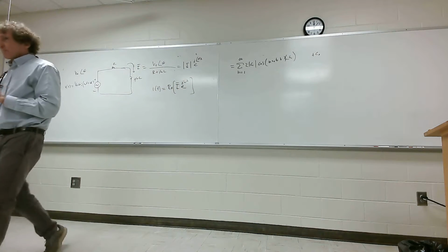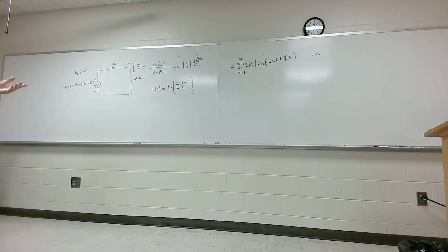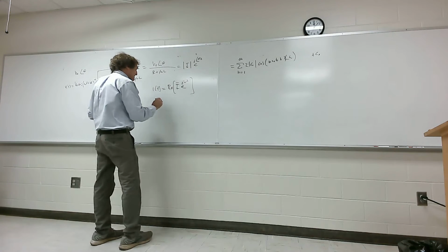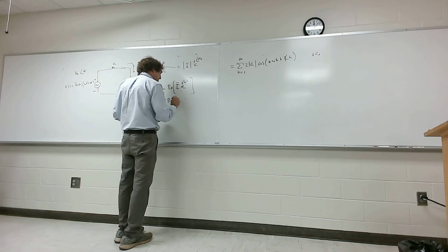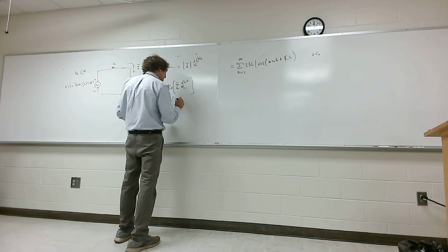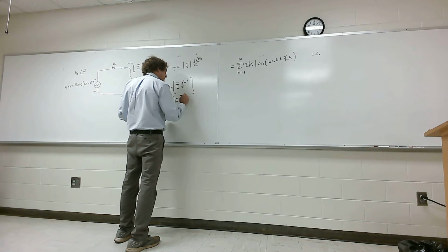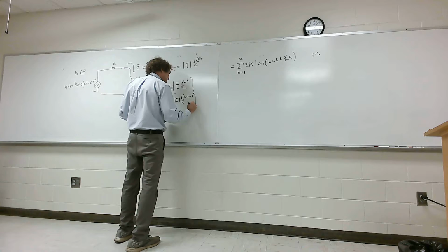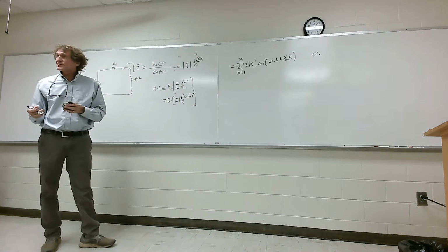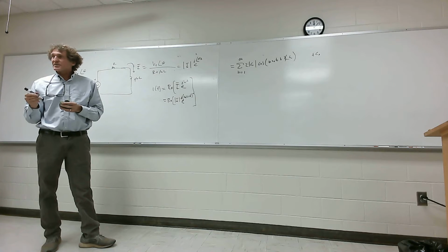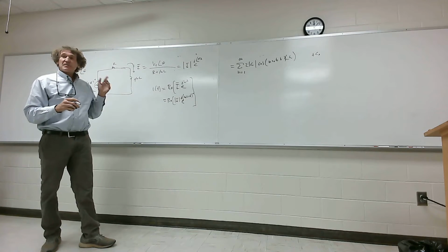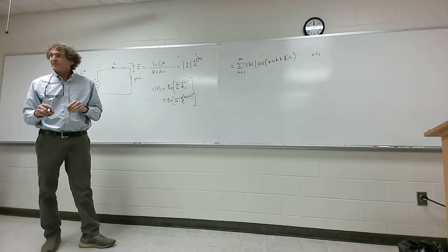Now, when you take a look at that, what does that automatically mean? This is equal to the real part of the magnitude of I, then I'm going to have e to the j, and this is going to be omega t plus the phase angle. Is it not? You can combine it like the exponentials. Please watch this. This is important. When people go out to interview, especially, and they fumble around with something like this, not a good sign. You should know this like you know V equals IR and that stuff.